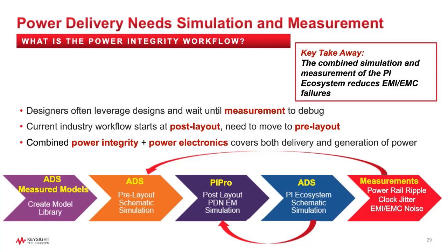This power integrity workflow looks great, but I am sad to say that there are many designers out there that just leverage a previous design or a datasheet example and wait until measurement to debug. This can be very risky and an expensive way to design. Some engineers use free tools provided by the power supply vendors like LT-Spice, but then they fail to simulate the EM parasitics of the printed circuit board and decoupling components. The PCB industry is focused on post-layout, since this is often where a manager needs to sign off and verify that the design is ready for fabrication.